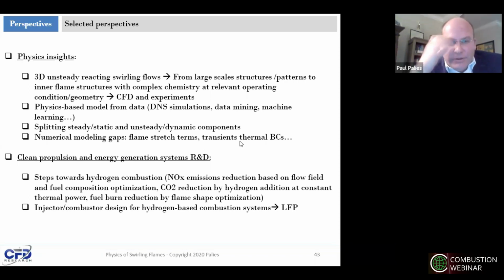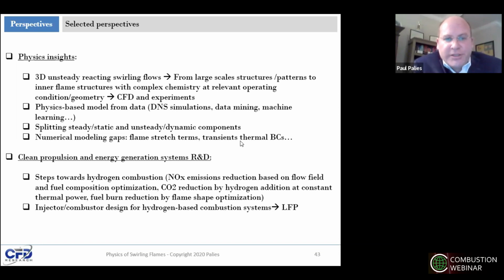You mentioned premixed combustion is not achieved. Is it also for gaseous fuel? Can you please elaborate a little bit more? Okay, so this question is important. As of today, there is no gas turbine premixed combustion system. At the laboratory scale, we know how to do premixed combustion, but in an aircraft or in a gas turbine energy generation system, there has been no technology to do fully premixed combustion.